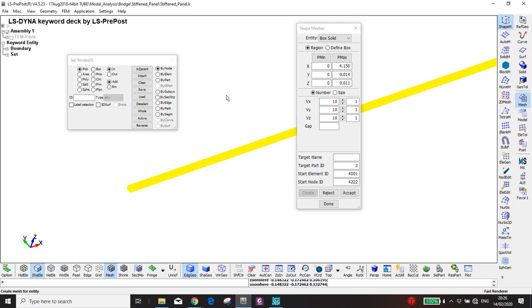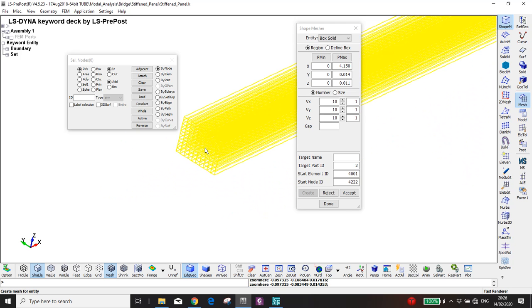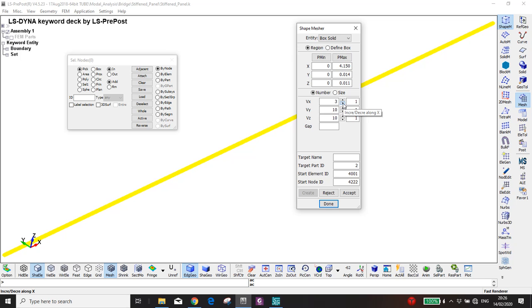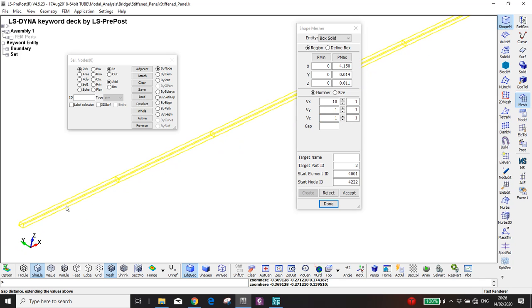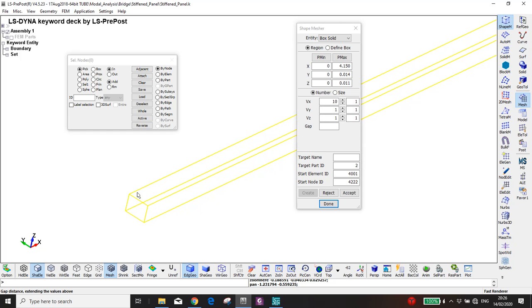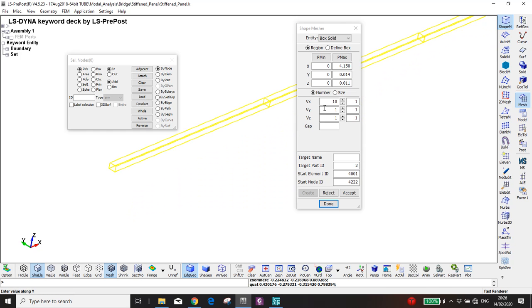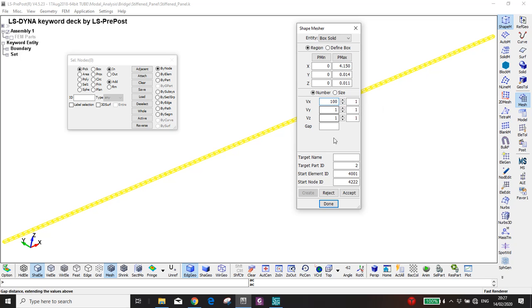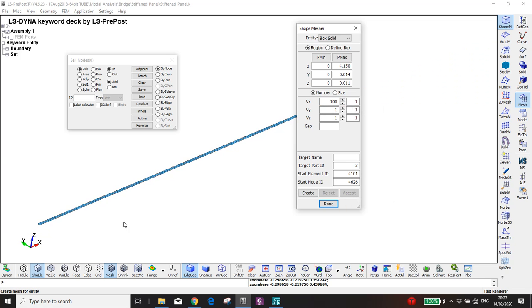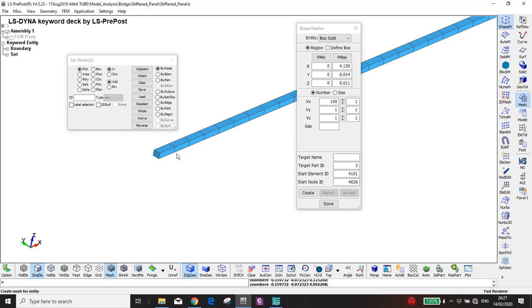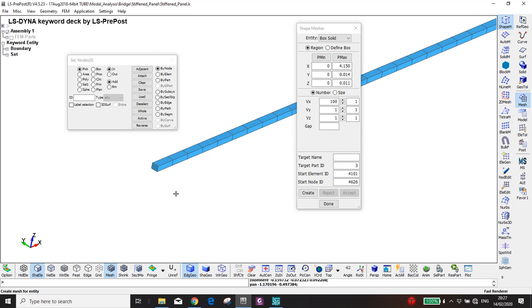You might wonder what is this long thing. Doesn't look like a stiffened panel, right? So no need to worry, just follow first. In x, you can increase the number here along the x, y and z should be 1. This is what we're making, just a box here. In x, let's say I make it 100. Yeah, should be fine. Now we can extrude to the top 200.